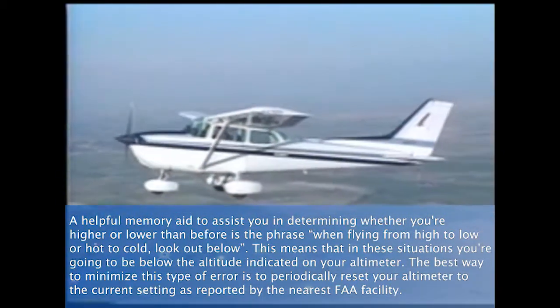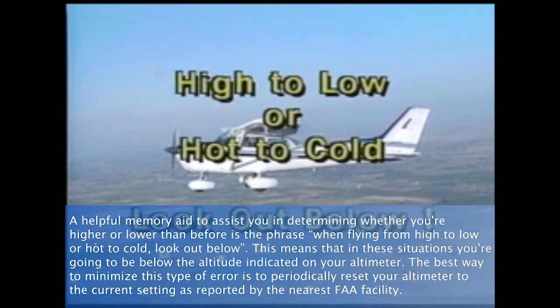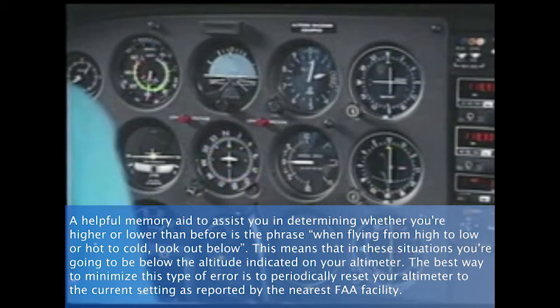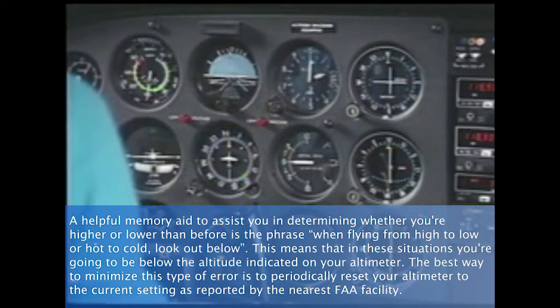A helpful memory aid to assist you in determining whether you're higher or lower than before is the phrase, "When flying from high to low or hot to cold, look out below." This means that in these situations, you're going to be below the altitude indicated on your altimeter. The best way to minimize this type of error is to periodically reset your altimeter to the current setting as reported by the nearest FAA facility.